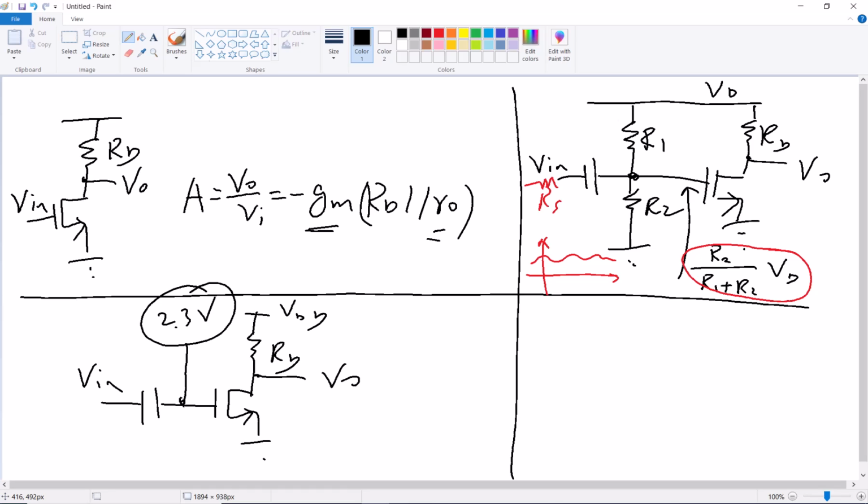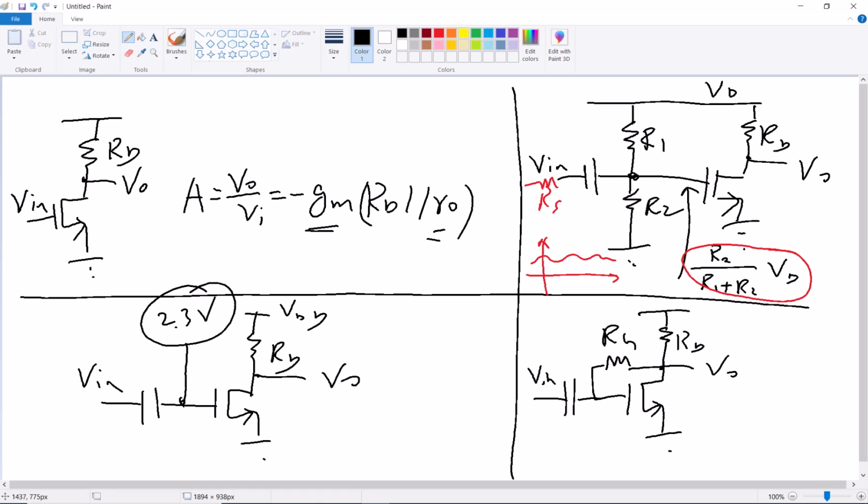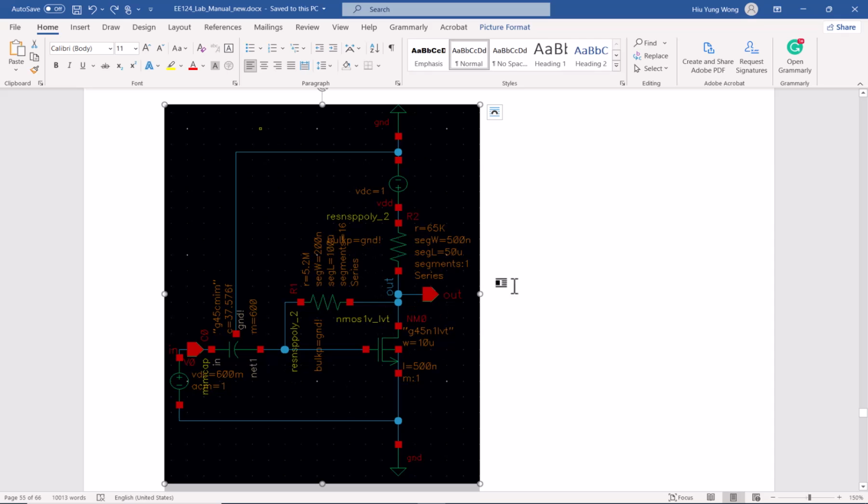That's why here we use the self-biasing. We have this RD here, and then we add the RG, and then we have the cap, and we have Vin, and then Vout. And this is the circuit we are trying to design here. So we need to get the capacitance right, get the RG right, otherwise it will feed through, and then also the RD. And that's it. So we have already done the design.